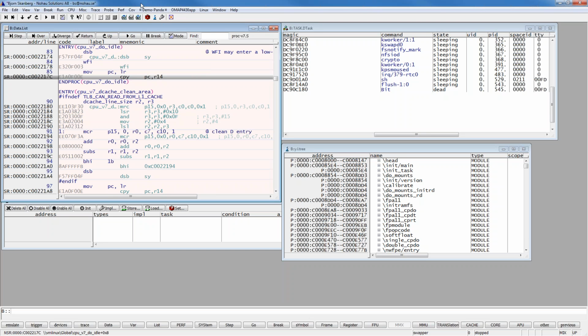If you have use cases that are quite commonly used, you can always go in and put them in the menu. And then if you have perhaps users that are not so experienced with the Trace32 GUI, they can just go ahead and click this menu, and it will set up the whole debug session for them, or it will take some ROM dump or do some error detecting or something like this.